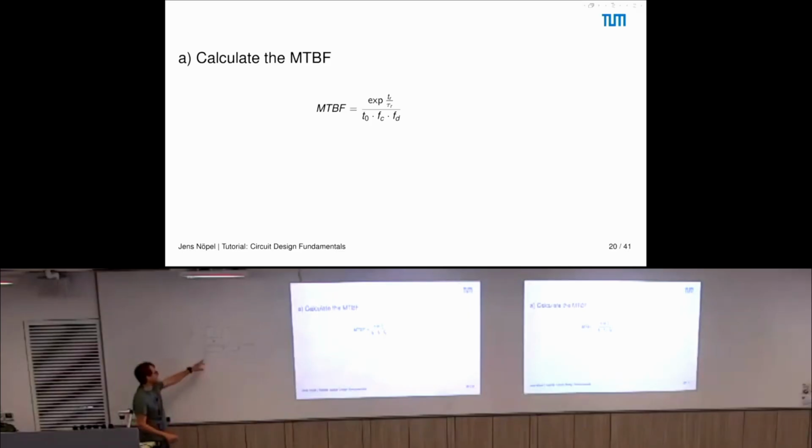Only if we sample this signal in this time window with Fc, which is our sampling clock, and a rising edge of this happens to be exactly in this time window, then we have the case where a metastable event can happen. In all other cases, it won't.